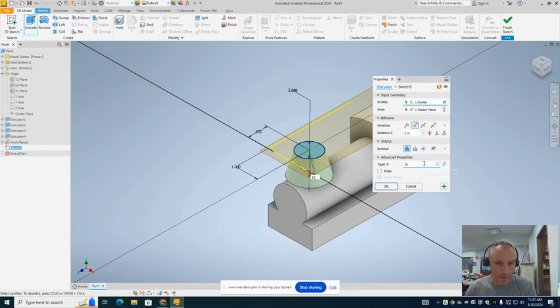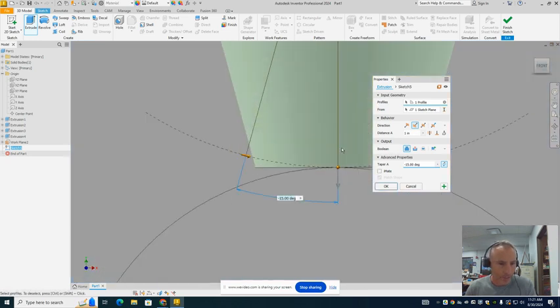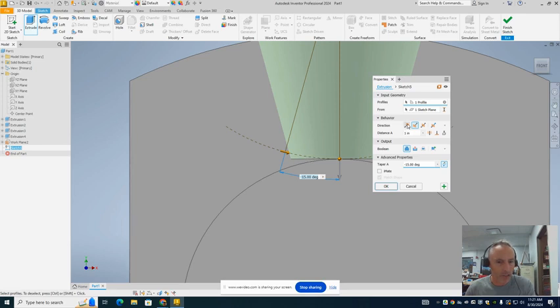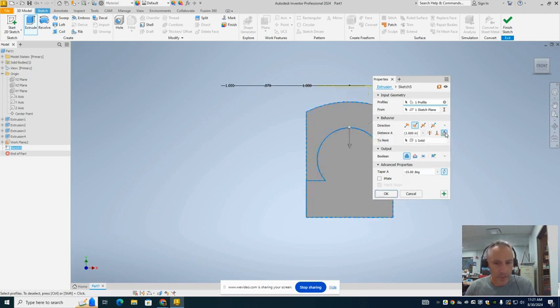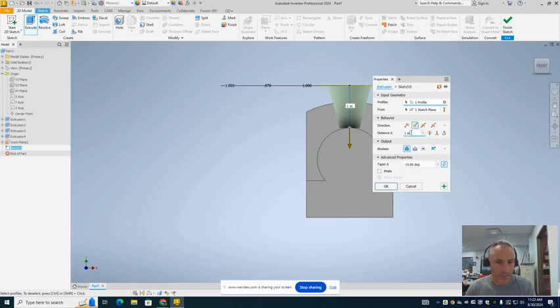Well, I didn't really want it to get bigger. I wanted it to get smaller. So we're going to flip that direction. And it looks something like that. Okay. But if you look, by coming down 1 inch, it doesn't quite actually merge because this was 1 inch. We were designing from 1 inch above. So we need to not go down just 1 inch. We're going to say go to next. Okay. Well, instead of just doing that, let's put it in 1.5, and then it'll be plenty.